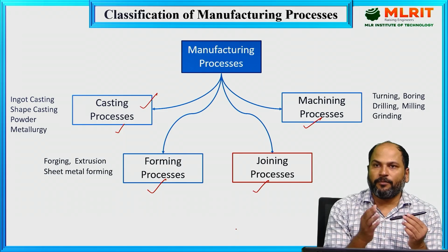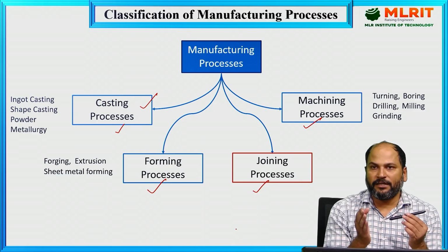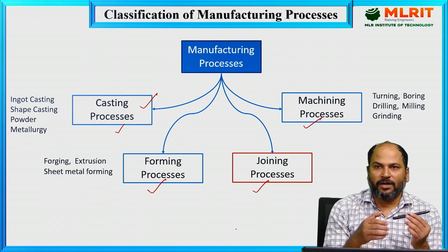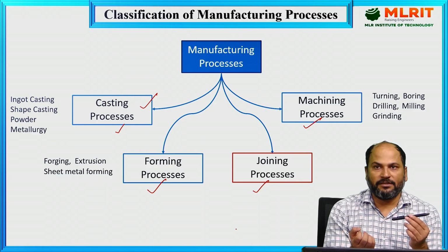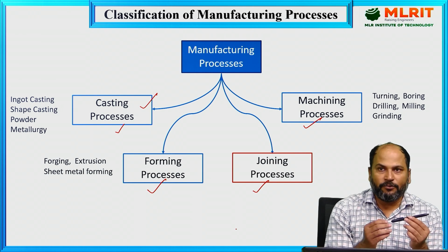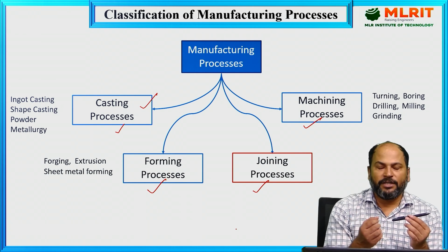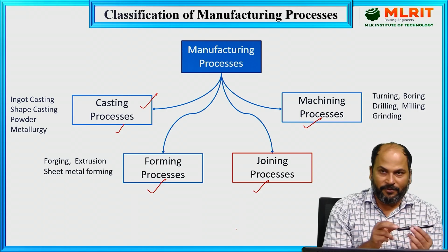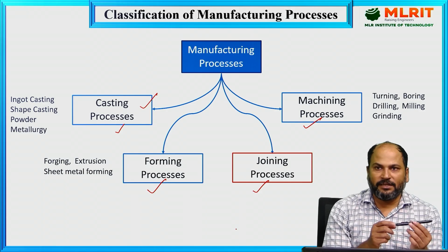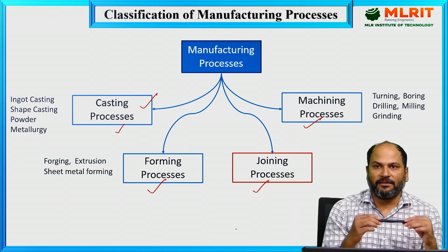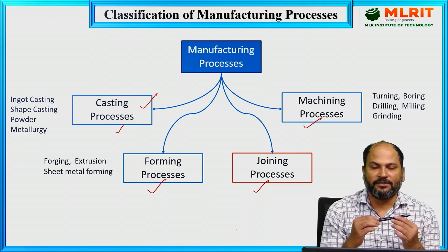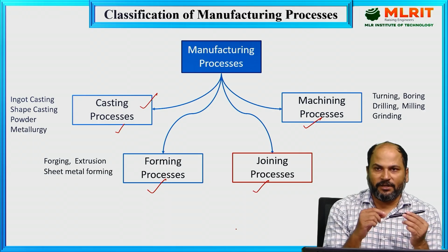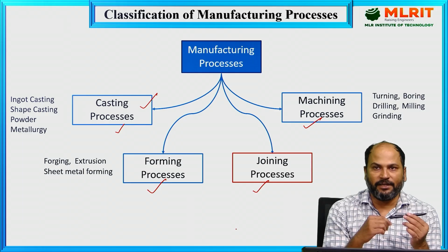Depending upon the application, what kind of dimension change we want in the material, accordingly we have to choose the forces. If we have to increase the length of this stylus, then we'll apply the tensile force and its length will increase. But to compensate for that, we know its cross sectional area will decrease.